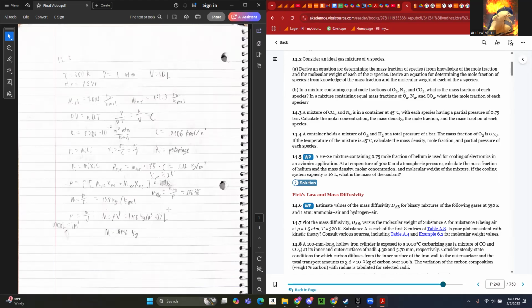So that's going to be about, not 100, like 0.01 cubic meters. I just plugged that all into my calculator, so I didn't see the actual volume in terms of cubic meters. But in the end, the final answer should be that the mass of the coolant is 0.0146 kilograms. Barely weighs anything. Makes sense with dealing with gases for the most part.